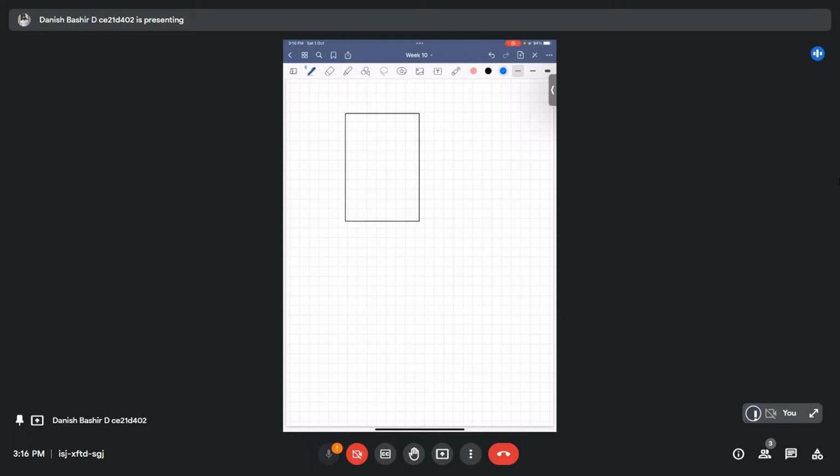Originally, our width of the section is defined by this width, the distance between the outermost edges, b. But when we have torsion, we also require another definition of the width of the section, that's b1. That b1 is given as the distance between the centroids of the longitudinal reinforcement. So the b1 here will be given by this distance.